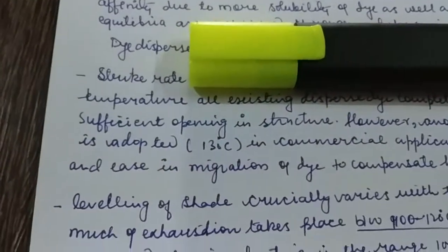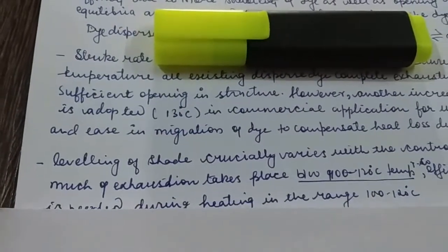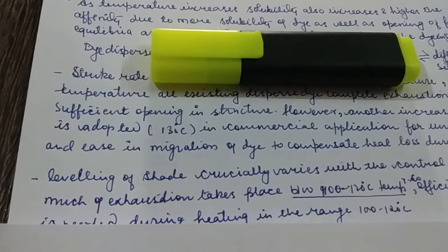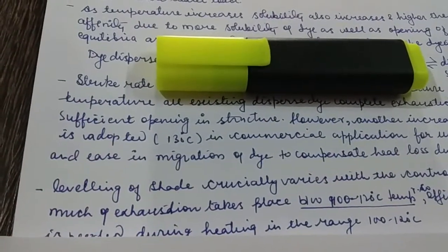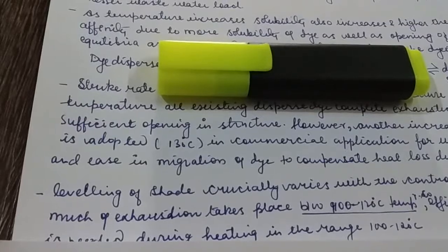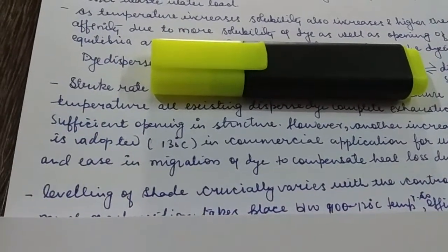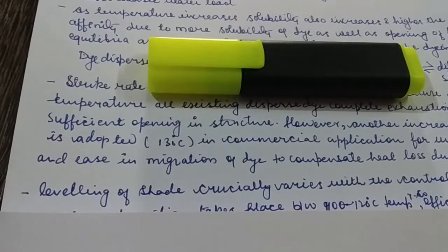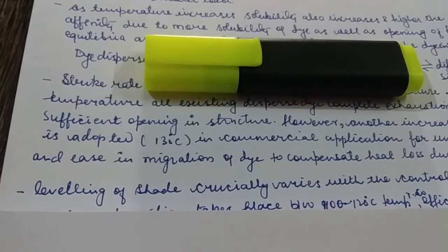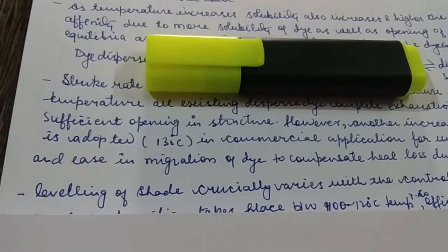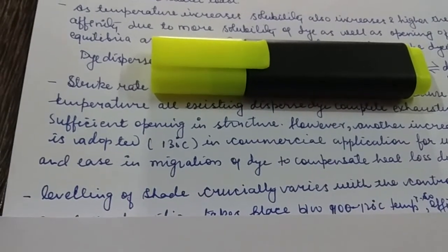So at high temperature there is oligomer formation, but when we drain the bath after cooling, at around 80 degrees centigrade, then the oligomers are deposited on the fabric surface. If we need no presence of oligomer on the fiber surface, then there is one option.